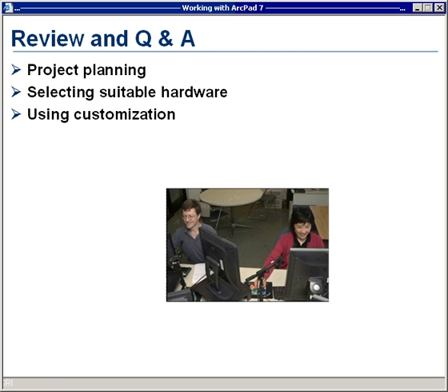Once you are back in the office and you wish to do post-processing, you need to add an additional step before you actually check in your data into your geodatabase. Using Trimble's GPS Analyst extension to ArcMap, you would first post-process your data collected in ArcPad, and then once you've done that, you'll update your data in the geodatabase.